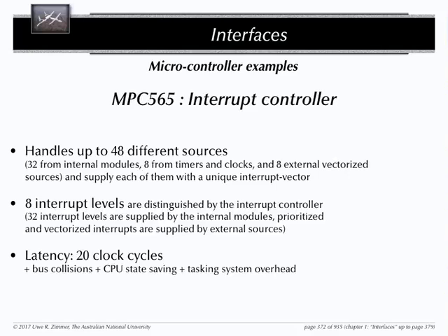Yes, you have usually also a guaranteed latency for the interrupt controller itself, that if you have a physical event hitting the controller from the outside, you have a maximum latency for the highest priority interrupt, so assuming everything else is of course unmasked, free to go through the whole thing, of maximally 20 cycles before you actually have the PC at the right spot and the thing is executing.